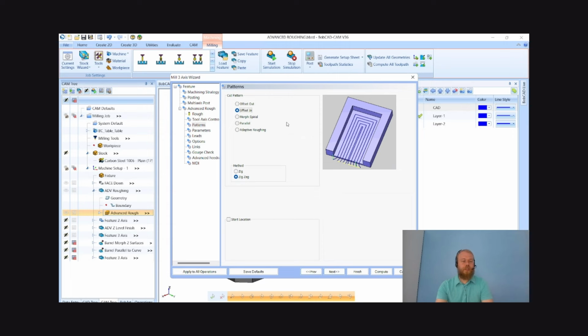And then we have our high-speed machining operations. This is where we're getting into controlling our feed rates and controlling certain things here. We have our high-speed machining options, which would be our morph spiral. The tool is going to start at the center, continually spiral its way out, keeping constant tool engagement instead of wasting time in those first 3 here, stepping over each time and wasting time that way. It'll continually spiral around, constantly engaged in the material.